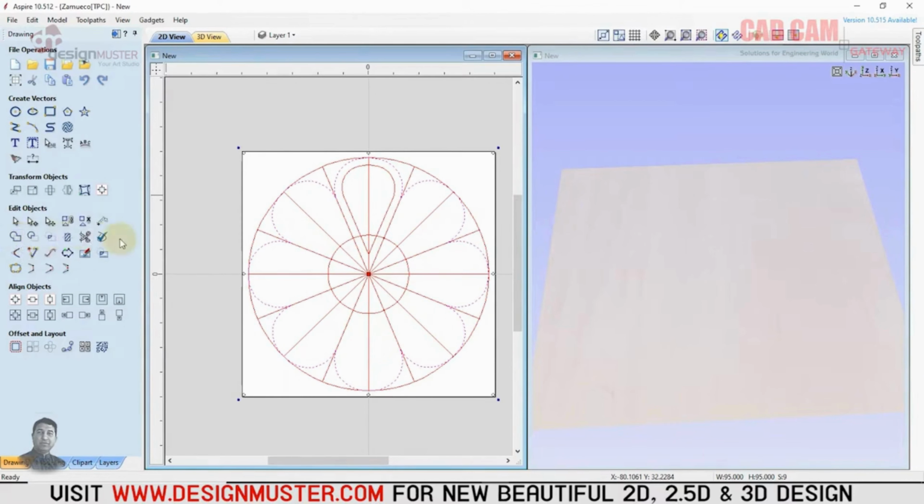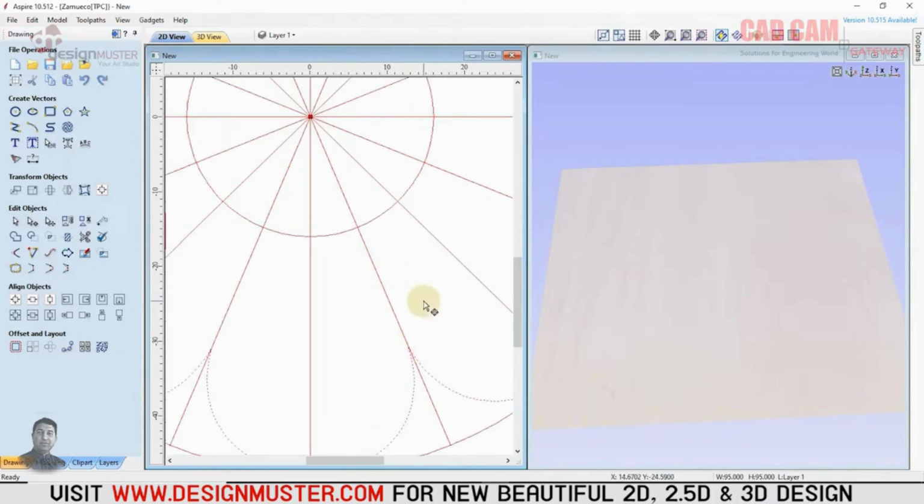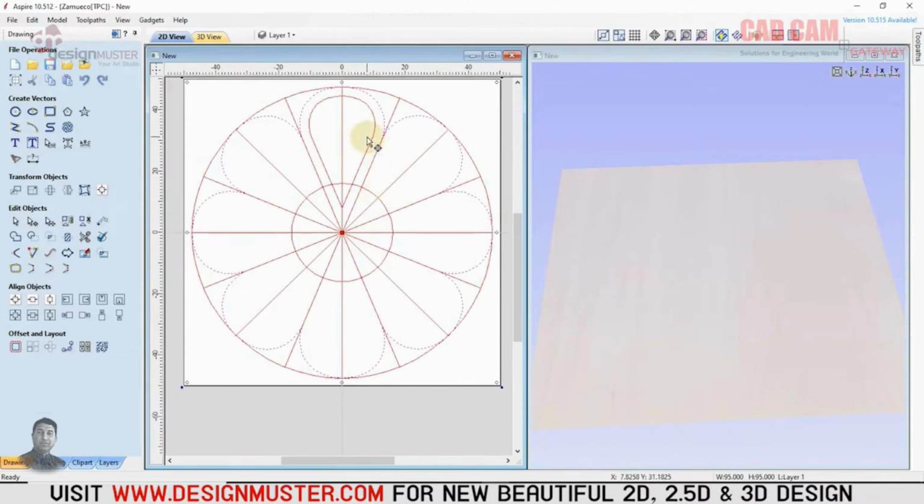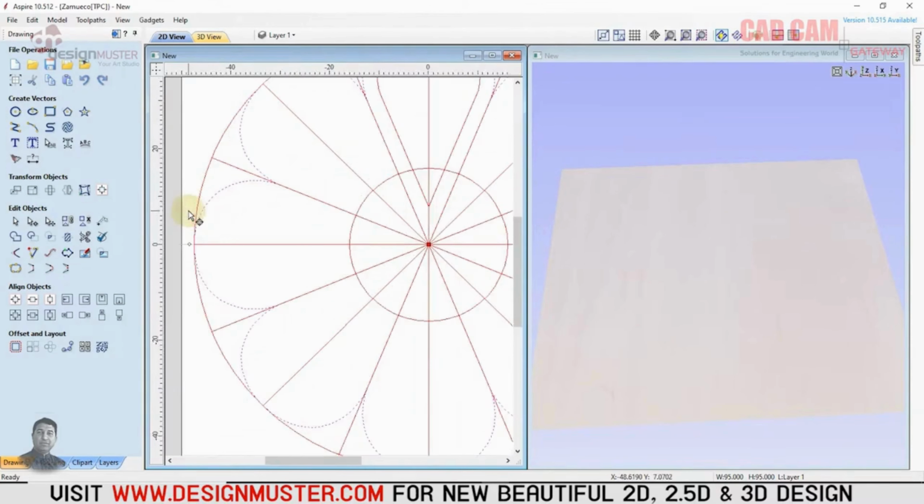After I did all this, see what happened. The zigzag pattern on the outside got completely separated. Look at this. If I hadn't placed this circle, these lines would have continued inside. I used this feature to remove those lines. So after all this work, you've saved one cross-section. Now we need to create the cross-section for its upper part. So let's come here, and at this spot, I'll create a cross-section.